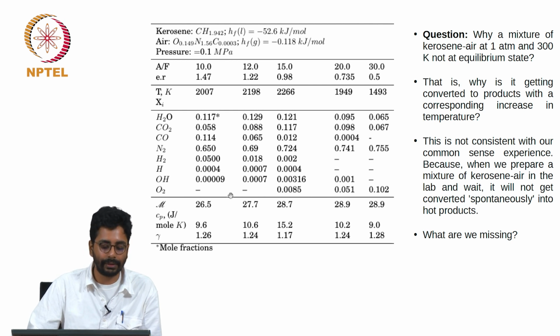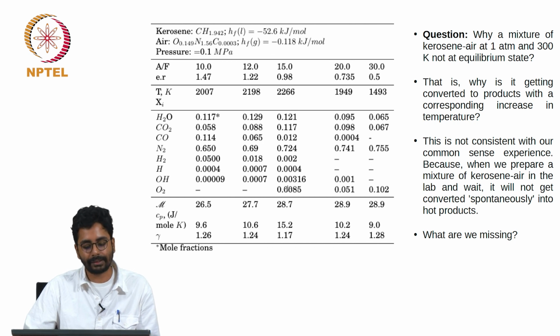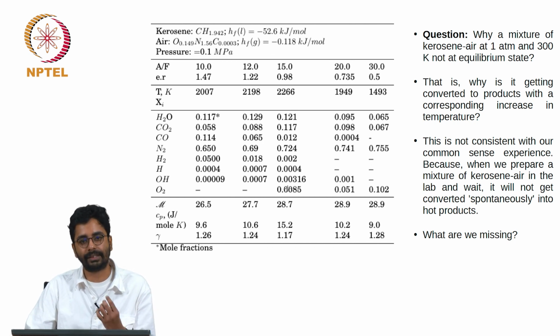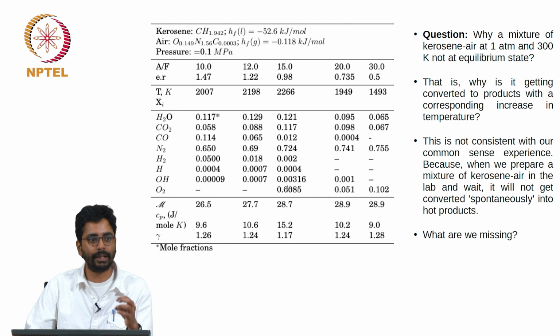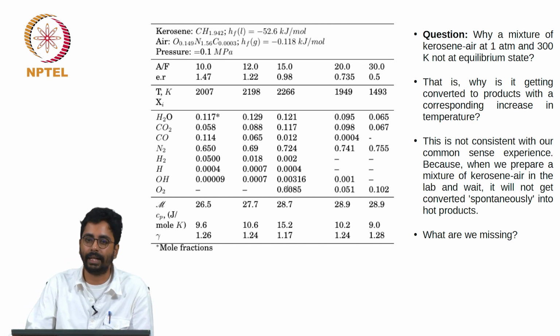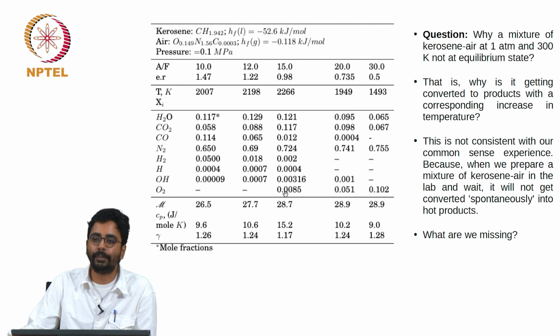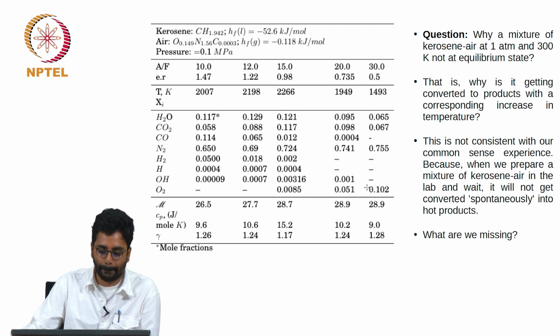There is no leftover oxygen when the combustion is rich. There is some oxygen left over at stoichiometric, because remember that the products are at very high temperatures and therefore dissociation will happen. Carbon dioxide will dissociate into carbon monoxide and oxygen, and water vapor can dissociate into hydrogen and oxygen. Therefore there is a little bit of oxygen present at stoichiometry. Of course the excess oxygen under lean conditions can also be seen here.